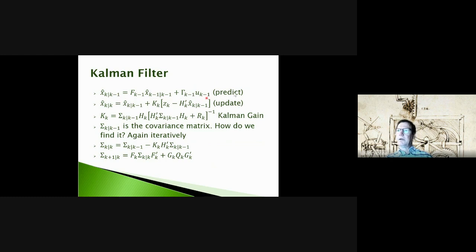So this is predicting where we should end up, right? And now we want to update that. So we're taking our sensor reading and subtracting this scaled version of where we actually think we are. This is where we think we've measured. This is where we think we are, and this h is just transforming the units to be the same scale.